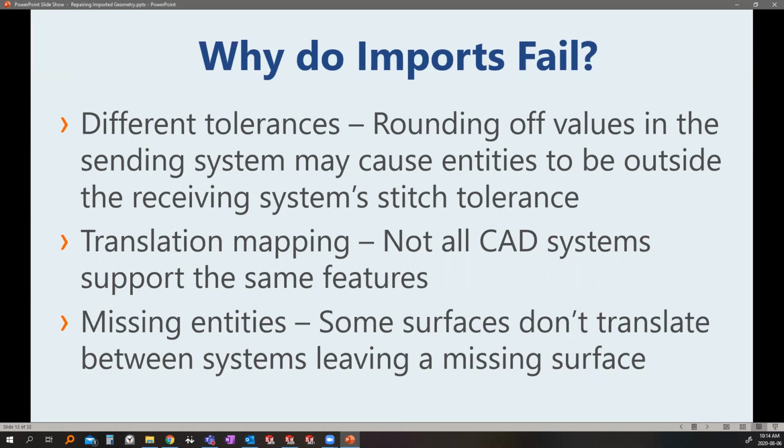If you are finding that you have wildly poor geometry that's getting imported, if you work closely with, say, your supplier that's translating out those files or exporting them, you can maybe tell them to go into their CAD package, whatever that may be, and to increase their curve tolerance. And that will give you a better import at the end of the day.